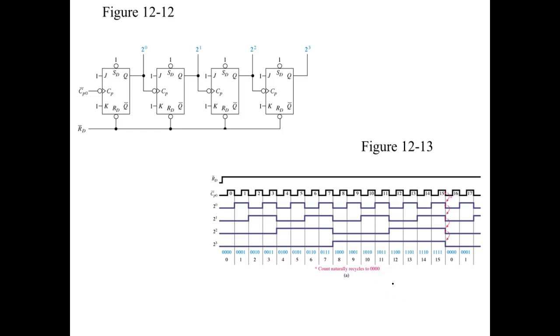And so what would be the modulus of this guy? Here we've got a reset, and how they tie the reset in and how they tie the feedback in to set the modulus on the counter is really no concern of ours. All we need to know is if it's a modulus 10, or BCD, or a modulus 16, which would be a binary count if it's a 4-bit count.